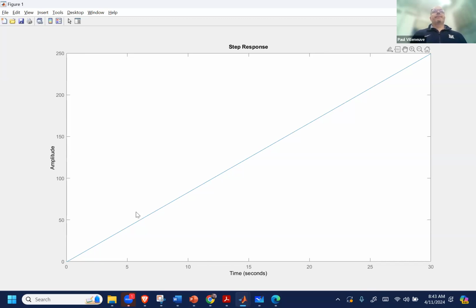And now, how do you estimate the overshoot? You don't estimate it, you actually read it off the graph. You know what the final value is, and you know what the peak value is. So you just normalize to that and use it as a ratio: take your peak value, subtract the steady state value, and divide by the steady state value.